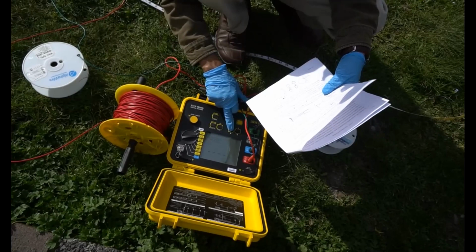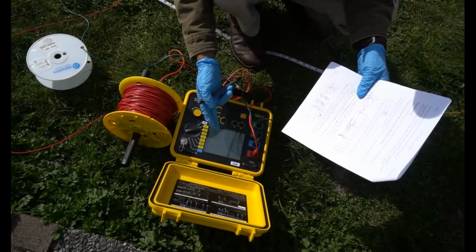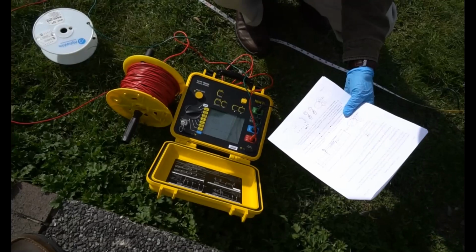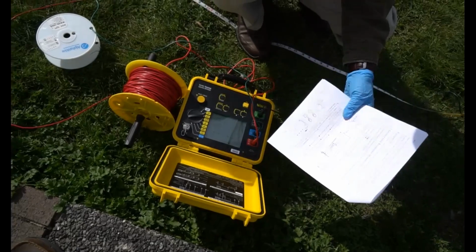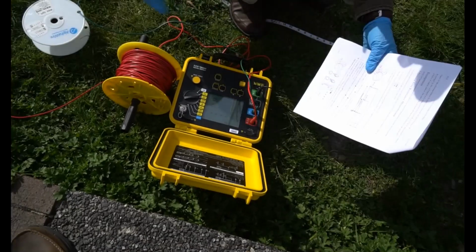So see, blinking will increase the distance: 10 meters, 20, 30, 40, 50 meters, and second distance again. This A represents the distance of the probe through which we will inject the current. That will be fixed, we won't change it, but this D will change. Each time we'll take a reading and the 5 meters will go away that way. So everything is set up.